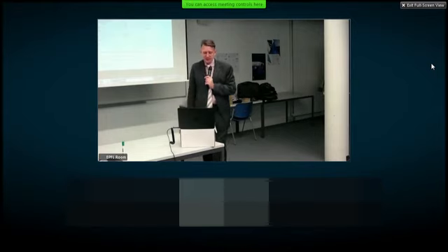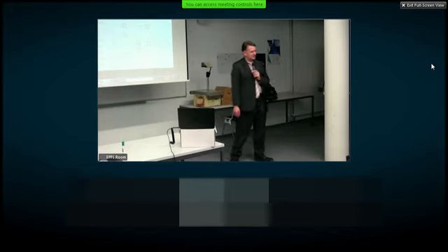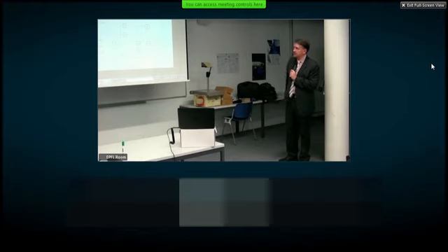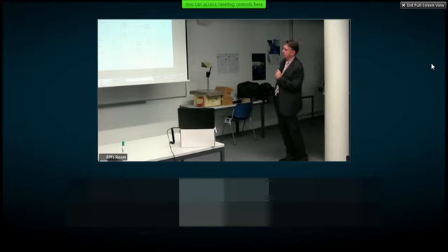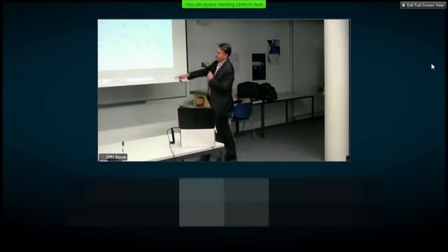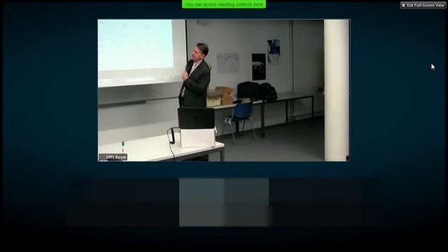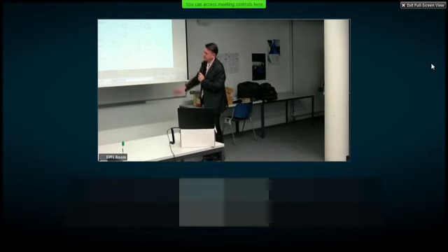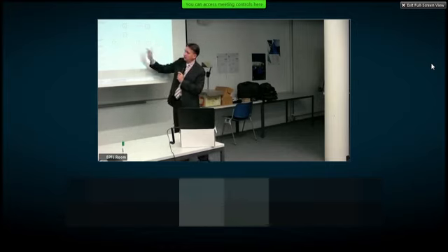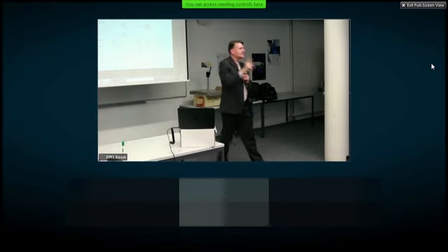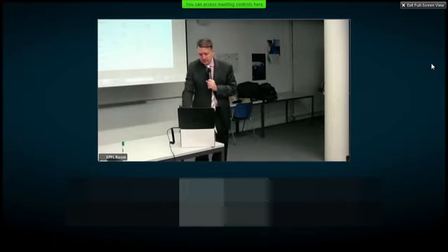So let's look at an example here. Do you remember the refrigerator case study we did a few sessions ago? This is a liaison diagram, level 1 decomposition. The refrigerator has been decomposed into 10 components: the door, the condenser, power supply, all the way to the compressor. And all we're doing here is saying what is physically connected to what. The reason it's called a liaison diagram is because it helps you think about the assembly sequence of how this should be put together. Another way to think about this is like the skeleton of your system.